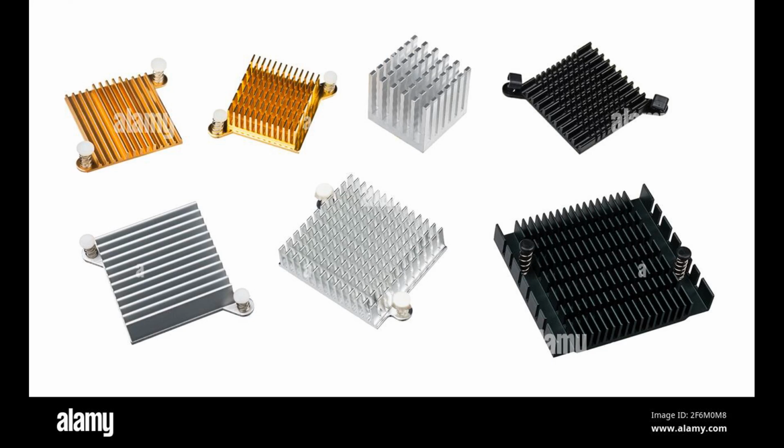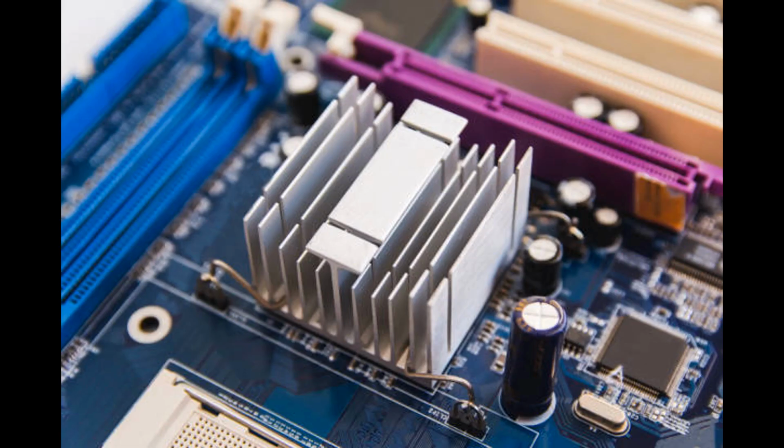Functionally, a liquid cooling heatsink works by circulating a liquid coolant through a network of channels or tubes that make direct contact with the heat source. As the liquid passes through the channels, it absorbs heat from the component, increasing in temperature. The heated liquid then flows away from the component to a radiator or heat exchanger, where it releases heat into the surrounding environment and cools down. The cooled liquid is then recirculated back to the heatsink to repeat the cooling cycle.